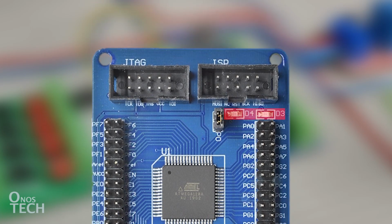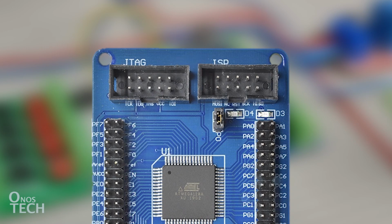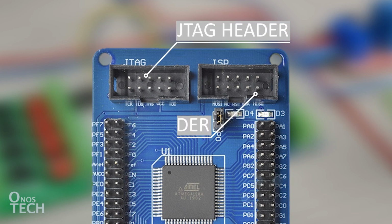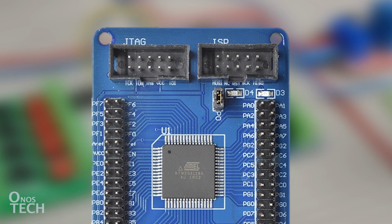These two onboard LEDs are connected to pin PA0 and PA1 of the microcontroller and are disabled by removing jumper P0. The JTAG and ISP programming pins are extended to these 10 pins header. The ISP programming pins of interest are the MOSI, Reset, MISO, VCC, and GND pins. See video number M1 for the serial adapter connection to the board.